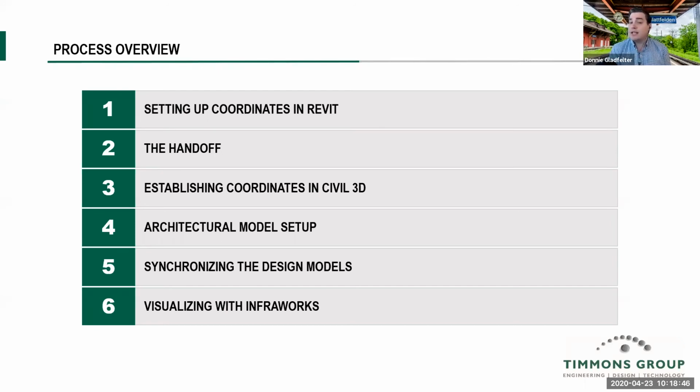Now, the essential task that the engineer did at this point was place the building on the project site. So they figured out the northing and easting of it, as well as the finished floor elevation. And this is one of the first big tripping points in project coordination: how do we communicate that information from the civil design into the Revit design? That's where we use the shared reference point tool to export that information in a way that, once we installed the same tool inside of Revit, we were able to import that into Revit from there.